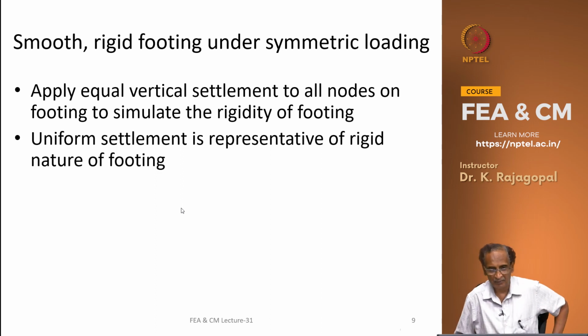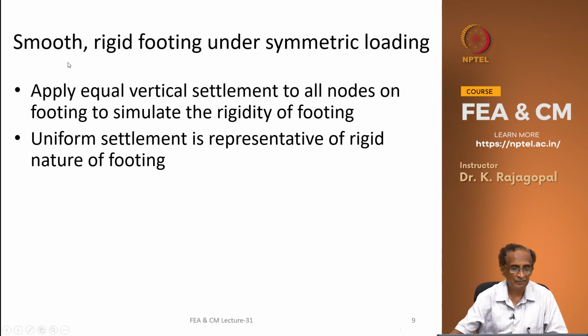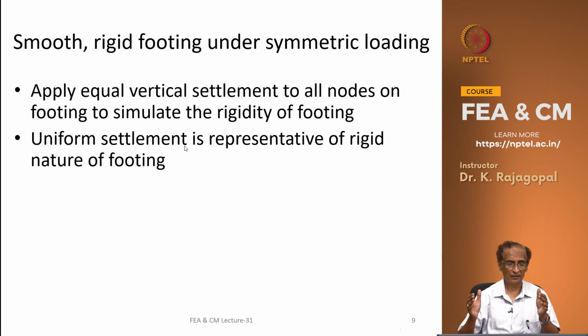And we can actually have different variations of the type of footings. Let us say we have a smooth and rigid footing under symmetric loading, and the rigidity of the footing we can simulate by applying equal vertical settlement to all the nodes on the footing, so that the uniform settlement is representative of the rigid nature of the footing.